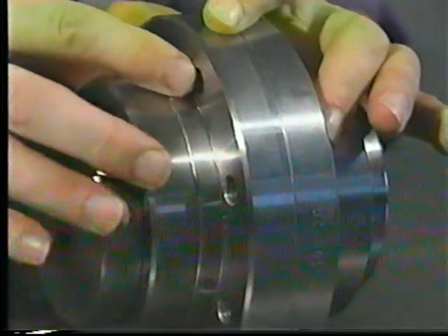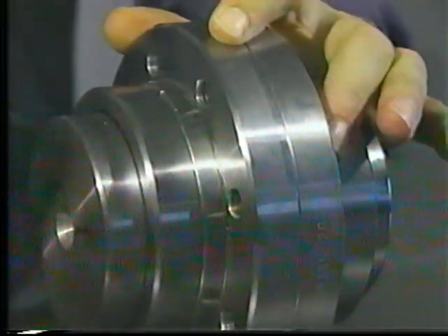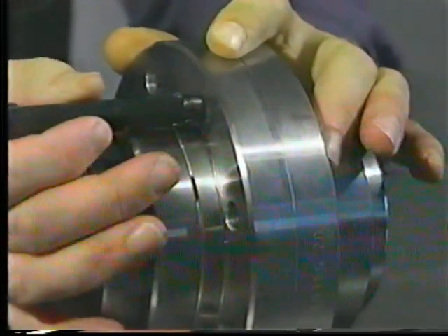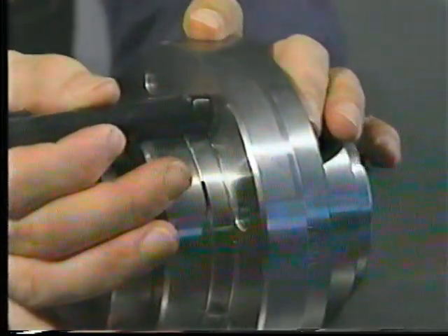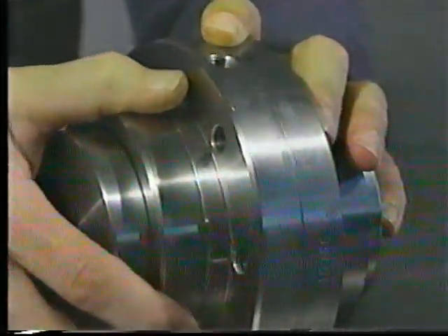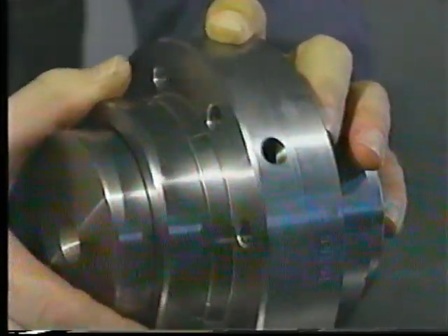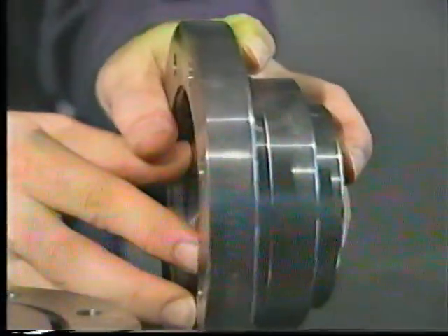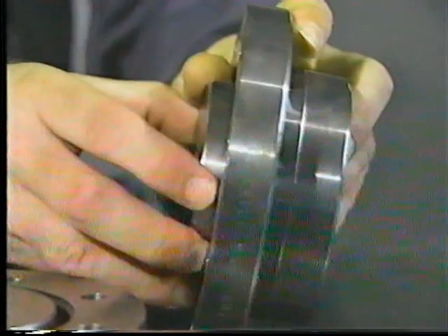The gear coupling can also be assembled with shear pins between the halves. Applying too much rotary force or torque to the coupling shears off the pins. The coupling halves, along with the shafts they are attached to, run free. A gear coupling with shear pins is used as a torque limiting device. Many gear couplings allow 1 full degree of misalignment.